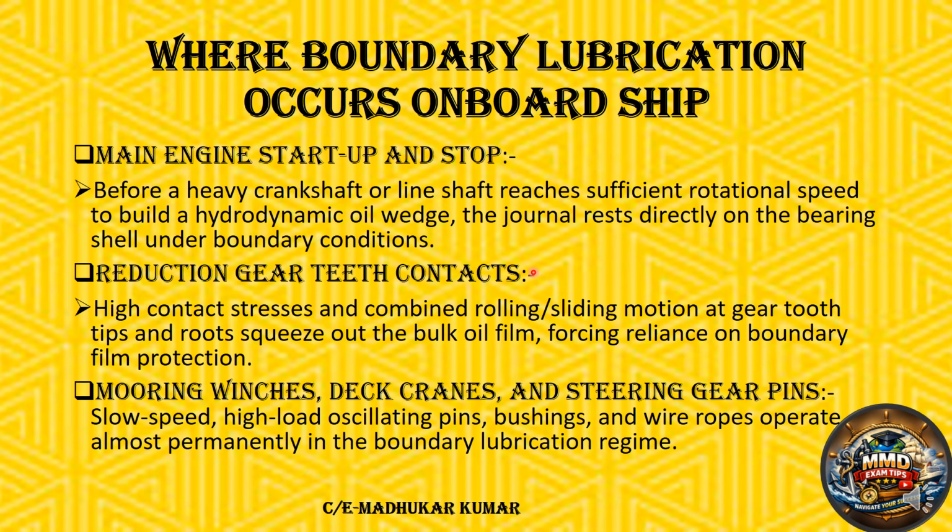Reduction gear teeth contacts. Yes, the teeth contacts between the gears. High contact stress and combined rolling and sliding motion at the gear tooth tips and roots squeeze out the bulk oil film, forcing reliance on boundary film protection. So there also you will have it. Once you inspect any gear, or a gear pump also, you will see the contacts between the gear teeth. This is the indication that boundary lubrication is there, and some microscopic contacts are established during lubrication.